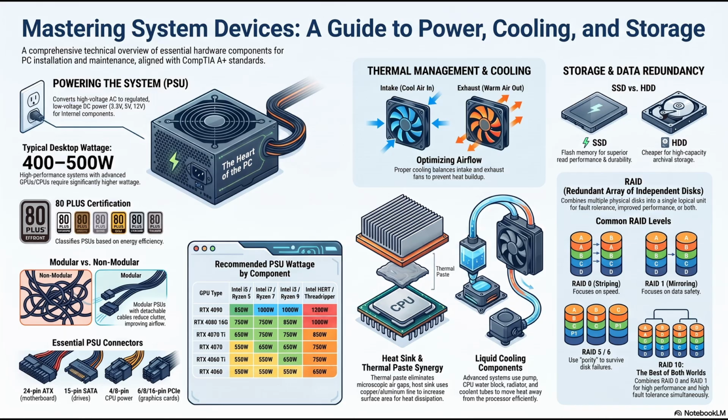A recordable disc, a CDR, replaces the stamped plastic with a layer of photosensitive organic dye. The laser in the drive powers up to a higher intensity and literally scorches the dye, turning it dark and opaque. The dark spot scatters the reading laser later, simulating a physical pit. But you can only burn it once. Exactly, the chemical change is permanent.